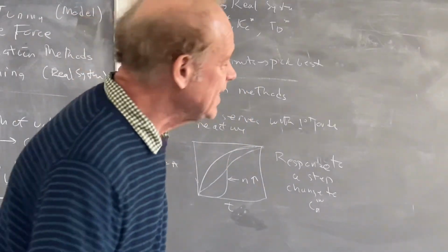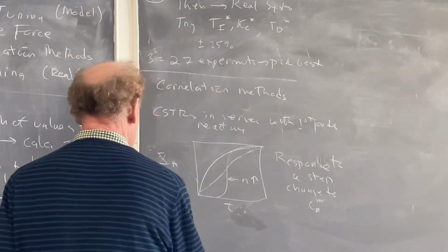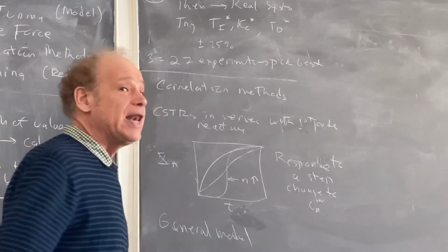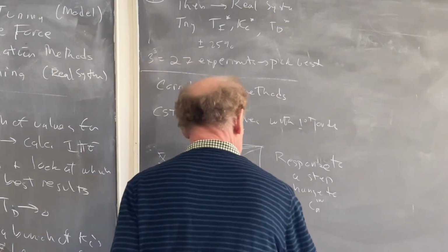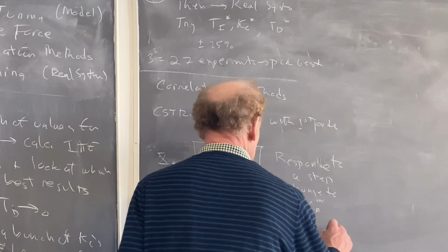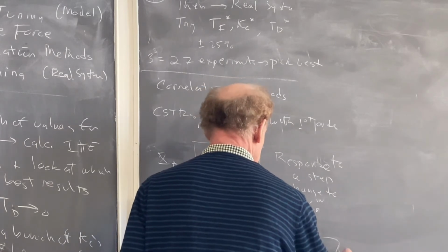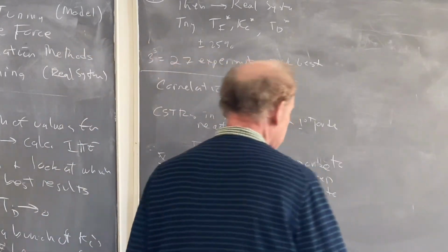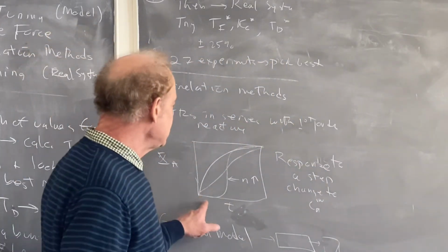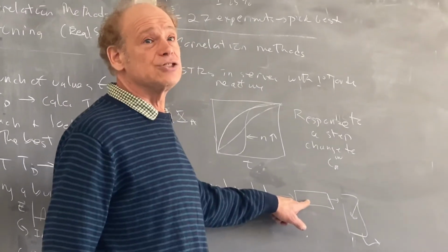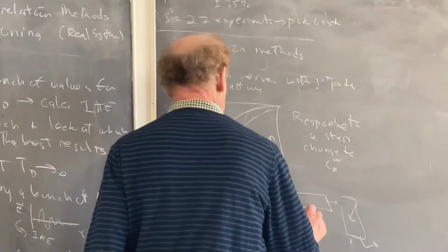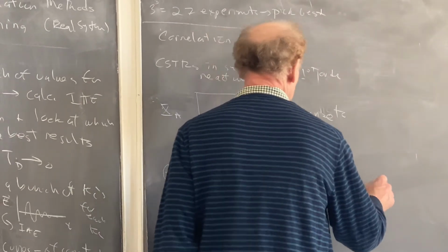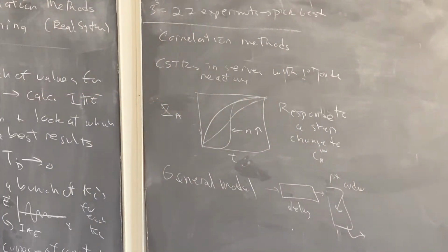So what that says is we can have a general model of any process as a plug flow reactor followed by a CSTR. Or the other way around, a CSTR followed by a plug flow. The fact this delay is essentially a plug flow is a delay followed by a first order reaction, a first order system. Now, why is that?